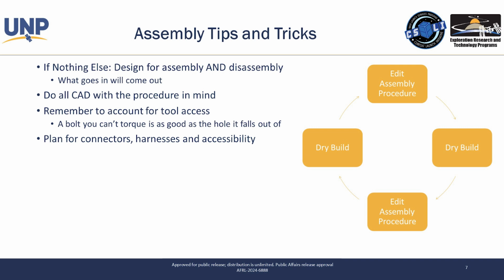Any of you who touch CAD for any reason must do this with the procedure in mind. These CubeSats are extremely small and very difficult for human hands, unless you have a really tiny engineer that you can use. And it's very common to forget that you actually need to torque the bolts and get a tool on them and be able to verify that the bolt is tight and Loctited and unable to back out.